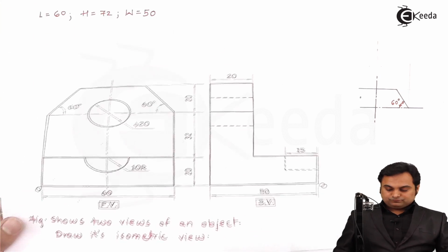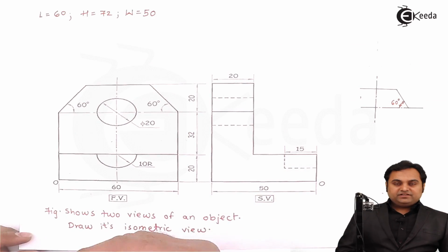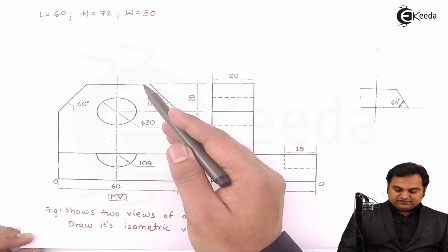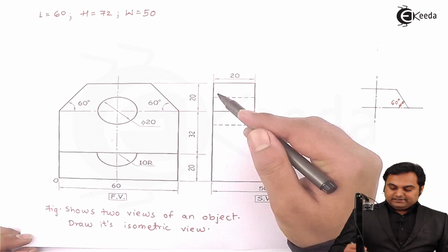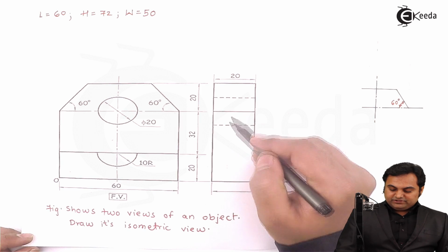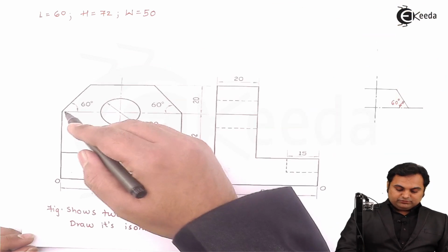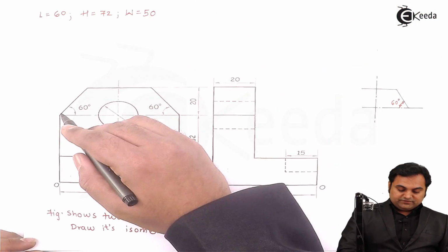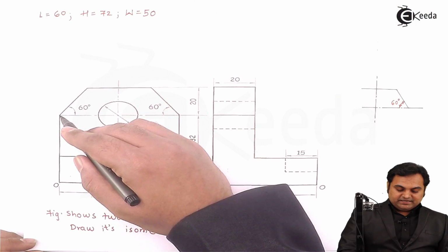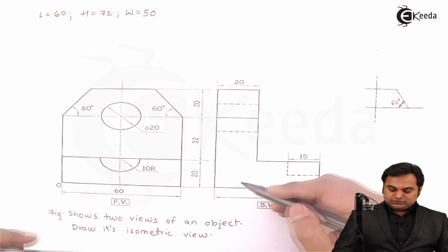Next, if we see this diagram here also, as the surfaces are inclined and in the side view there is a dark line between these two surfaces, that indicates change of plane. So when I look into the front, I can say that the surface which is at the top is inclined, and the bottom surface is straight, which is vertical.